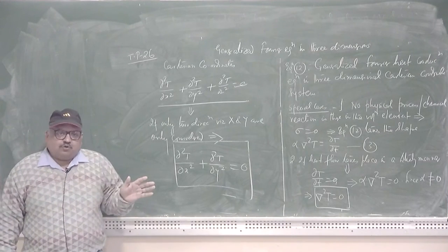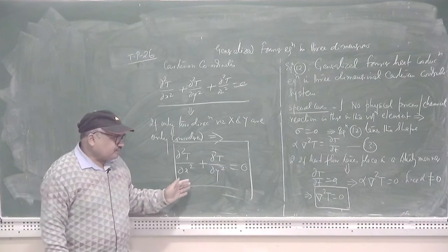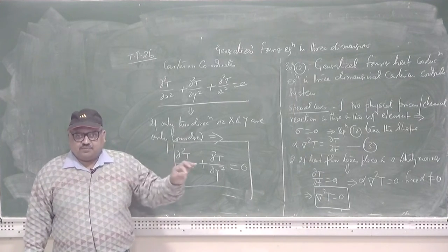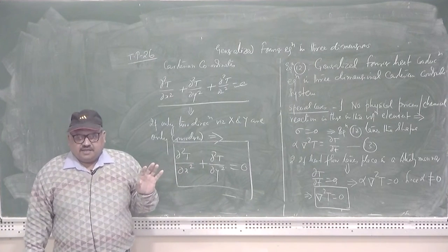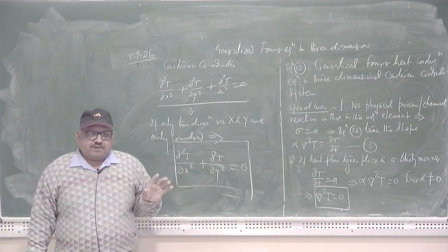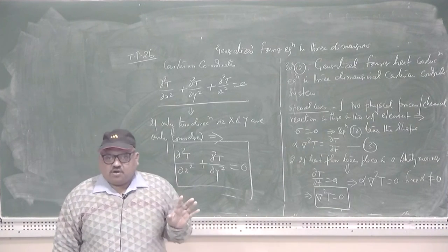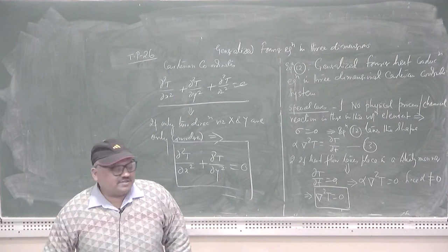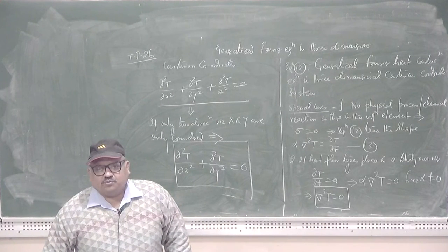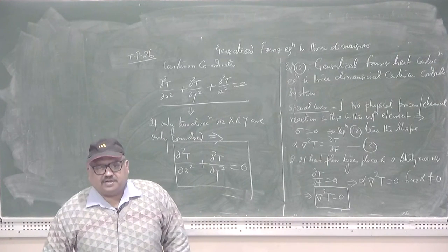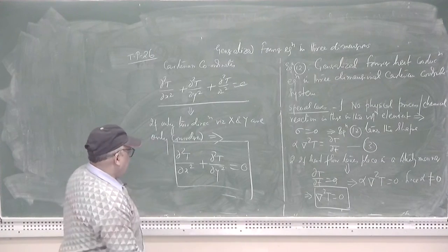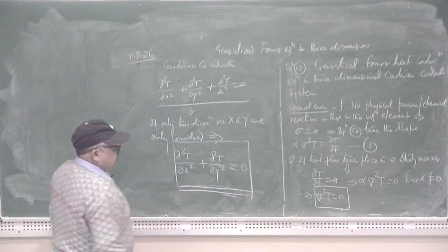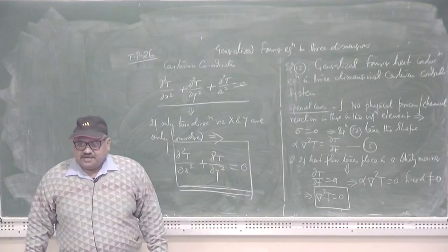The solution of those equations in terms of the temperature of the various nodes T1, T2, T3, T4, T5, etc. You can solve those equations by the Gaussian elimination method, and you can also utilize the matrix formulation method, X is equal to inverse of matrix times the temperature. So, you can determine the temperature at the various positions in a 2-dimensional plate.